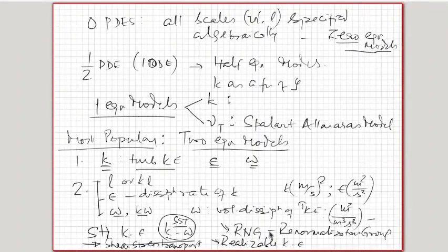So the common thing about all of these models is that the average terms, that is the mean terms, are solved using the equation, and fluctuating terms are always represented using an approximate model. Okay. Well, I'll close this lecture talking a little bit about boundary conditions of these flows.